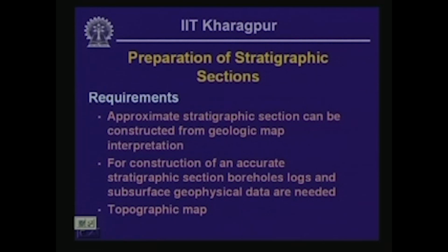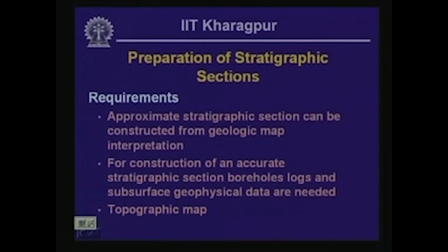Now, if you need to construct an accurate stratigraphic section, then boreholes need to be drilled and accurate logs identifying different stratigraphic units within the borehole will have to be prepared. And also in this context one might use subsurface geophysical data in which one can see different stiffness properties, stiffness contrast of different stratigraphic units underground.